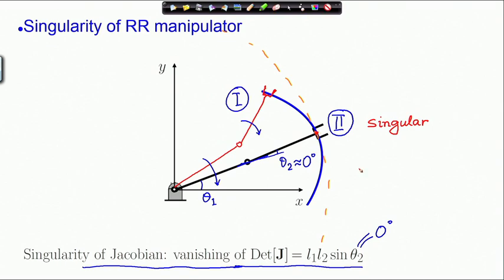So, therefore, the manipulator goes to a singular configuration. At this configuration, if you want to proceed further on the path, which again actually comes into the workspace, as you can see, it touches the workspace boundary and then again comes inward into the workspace. So, therefore, it can be continued. So, at the workspace boundary, either you can actuate theta 1 or you can just actuate theta 2,